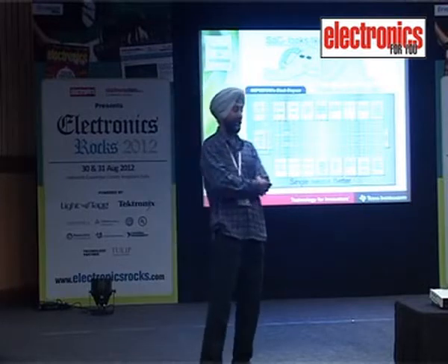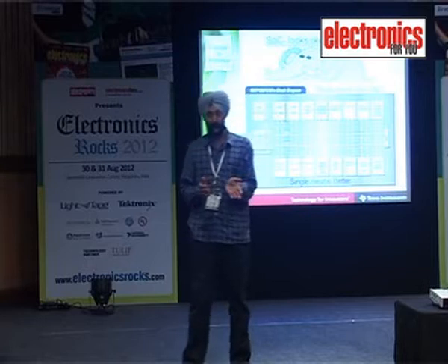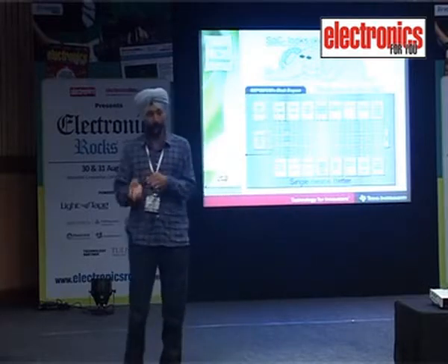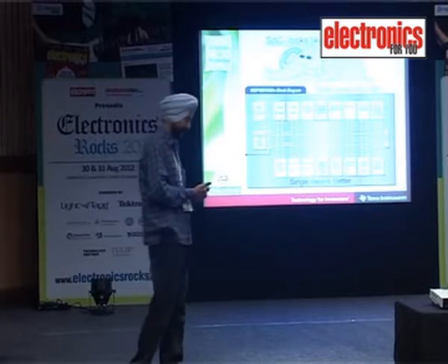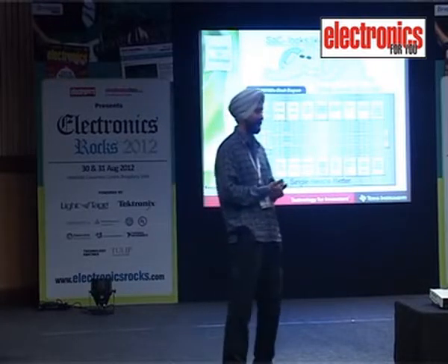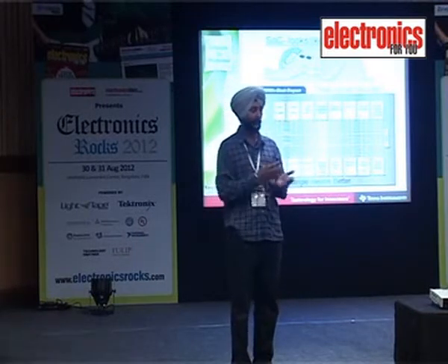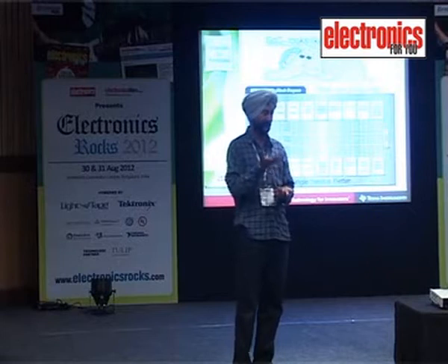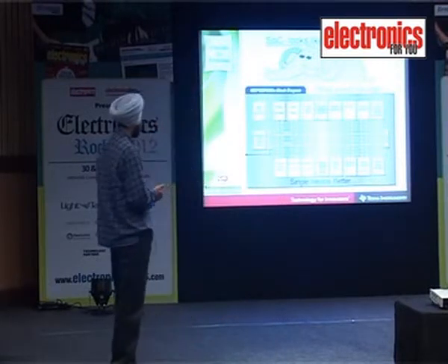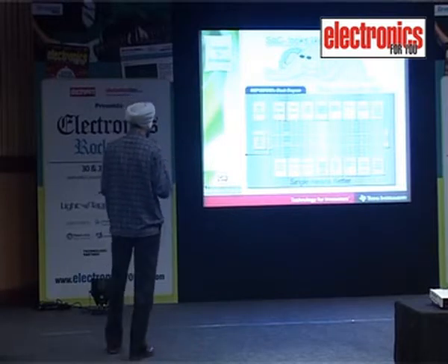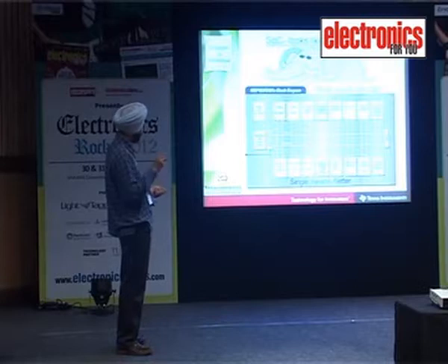So higher the frequency, higher will be the power consumption. So dynamically, you will be able to switch between high speed clock to low speed clock to the built-in clock DCO. You can use DCO also, but the problem with DCO is because it's an RC based oscillator. Normally when the battery voltage is changing, when your temperature is changing, you can experience this small variation in the frequency. So in some of these sensitive applications, we can always switch back to the crystal oscillator after the transmission